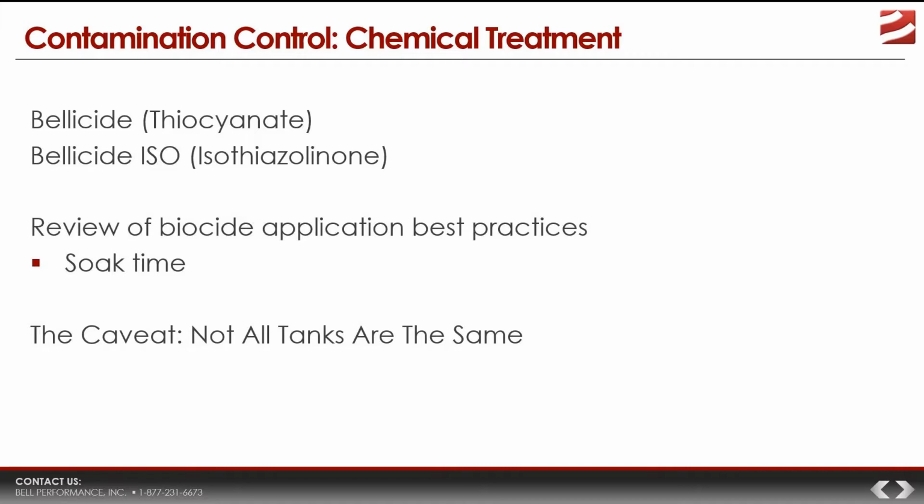Not all systems have the same amount of microbial contamination. You could have a heavily infected system, right? Is that going to require the same soak time? Well, no. Intuitively, we know that we're going to have to change some things up. So if you have a heavily infected system, you may have to wait longer. And you've got the whole plugged filter thing. Because remember, it kills the microbes, but the microbes still have to go somewhere. So if you had a heavily infected system, not only would you have to give it adequate soak time, but you would plan on having plugged filters until the killed microbes and associated biofilm have been flushed from the system.